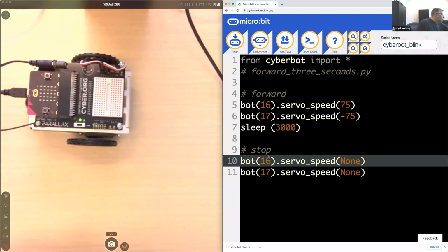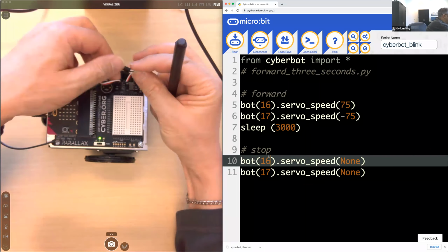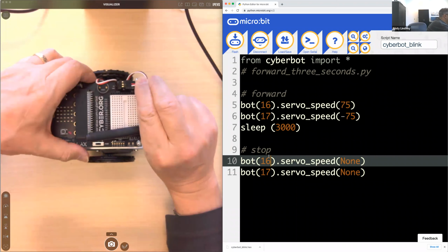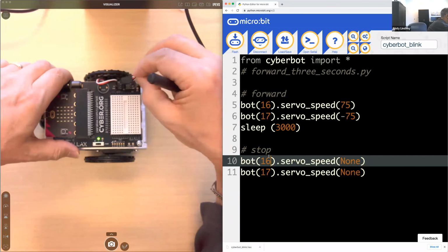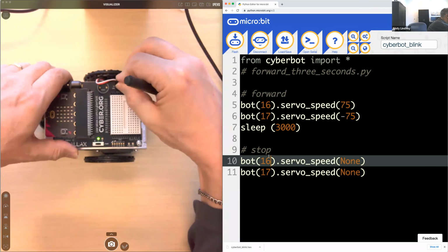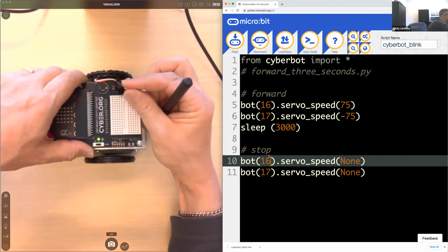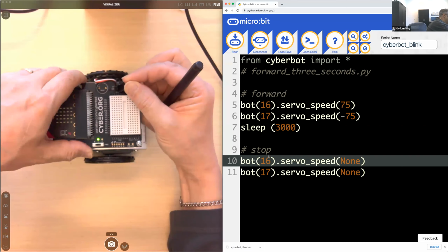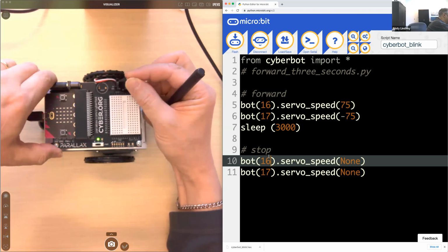Now, the other thing is, if only one servo is turning, it could also be an error, like maybe having it plugged in so that the cable is from top to bottom, black, red, white, instead of the way it should be, which is white, red, black. So check that first. But if you're confident that this is correctly connected, another thing that sometimes happens is you can end up shifting this way or this way a little bit on the pin, and you'll end up only covering 2 of the pins with the 3-hole socket instead of all 3.